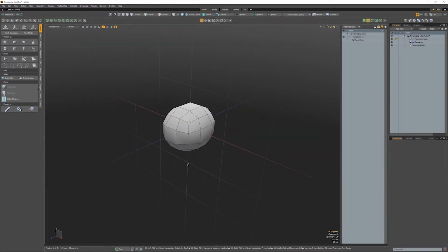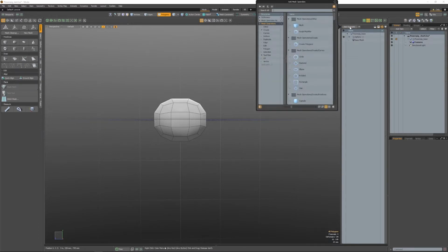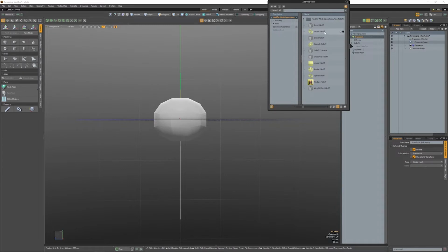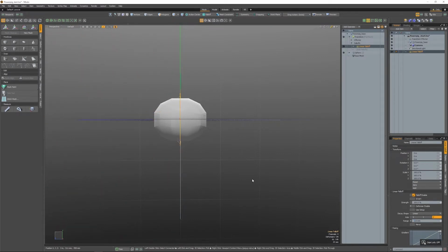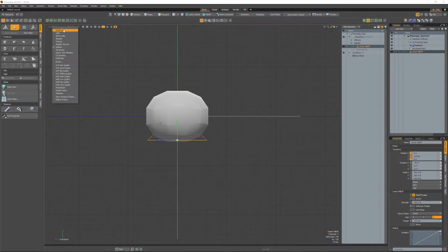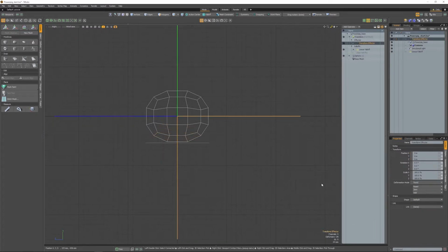So the next procedural operation that I'll need is to make the bottom of my power pig a little bit flatter. I don't want it just a perfect oval. So just load the transform, come here and apply a falloff. The falloff comes in also too big, so just change it to about 120 millimeters and rotate it. Just E for rotation, rotate it 90 degrees, W to move and move it down. I will increase it slightly, yes, now it's all right. And the next step is coming here to the transform effector, and I will reduce the scale on the y-axis. Something like this seems about right to me. Yes, okay.